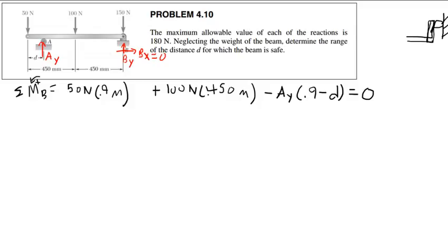We can actually take moments about any point. It's just a matter of there are certain locations where it's more advantageous to take moments. I took moments about point B because then that eliminates the reaction from point B from that equation, yes. Would it be useful at all to sum the forces in the Y? We could sum the forces in the Y, but the problem with that is that then we'll have two unknowns in the equation. Okay.